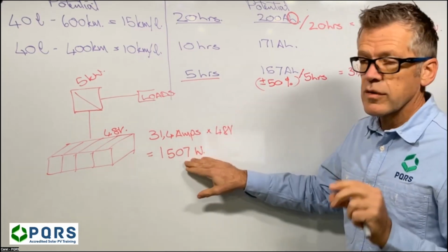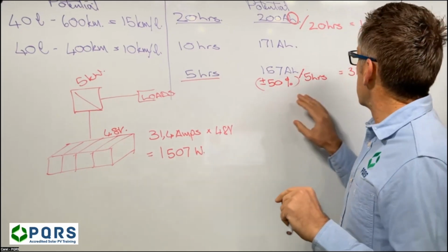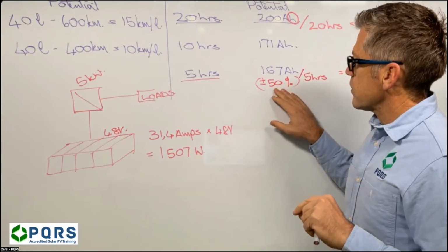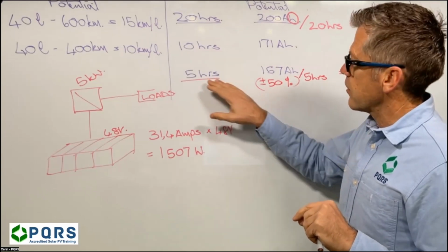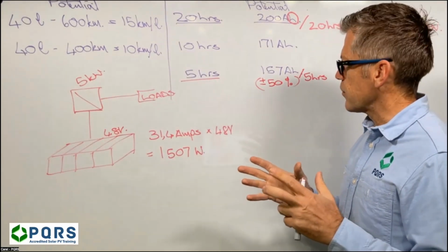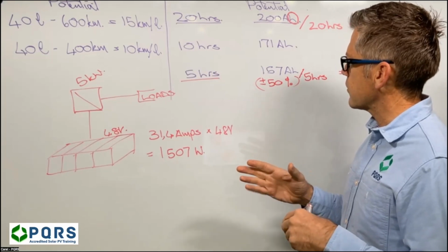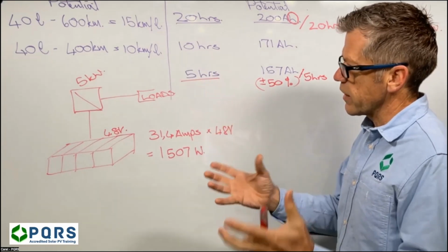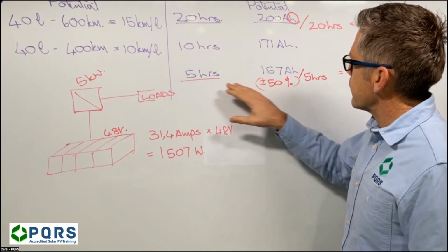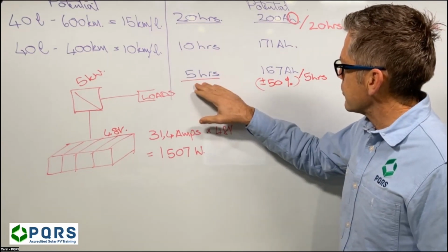These batteries will last 2 hours. And then they'll be at more or less 50%. I know over there it says 5 hours, but we allocate some time for losses. So in this case, we'll just leave 1 hour for losses. We've got 5 hours of discharge.